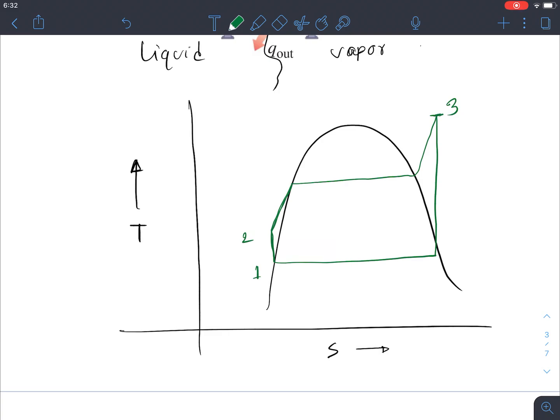You see that this is not anymore the isothermal process, right? So the temperature is maximizing, and this is number 4. At the turbine outlet, it's slightly coming to the moisture region or the saturated vapor region, right? So that's the TS diagram.